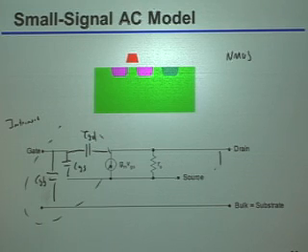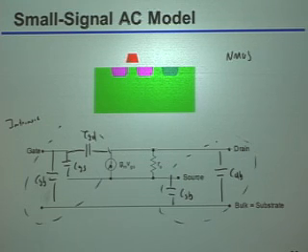Yeah, okay, so there's a drain to body junction capacitor. Anything else? Yeah, of course, say source to body, CSB. Okay? And so, by the way, these are so-called extrinsic capacitors because, unlike the other case, they exist, but one could argue that fundamentally they don't have to be part of how the transistor operates. They are indeed there, there's no real way to get rid of them, but they're not intrinsic to the operation of the transistor.